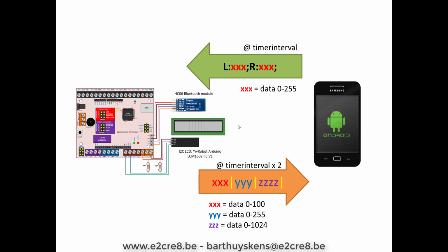Arduino board actually. Something that I need to say about timing here: if this data is sent, for instance, every 100 milliseconds, then the Arduino needs to read data every 50 milliseconds, and the data that the Arduino can send back to the Android device cannot be sent any faster than with 200 millisecond delays. So 2 times slower than the sending, for the App Inventor app on the Android device to be ready to receive new data. This is all, yeah, experience. So maybe you know of different ways, but this works for me, and this is the first app that I get and keep working for a long time, and that keeps stable. So hopefully it will help you.